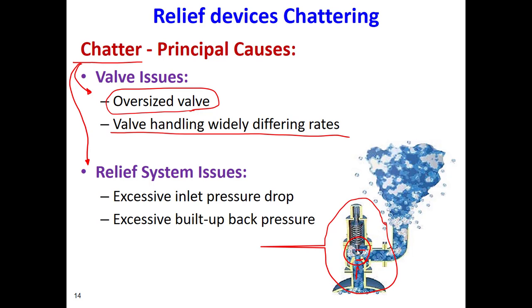Okay, in the inlet and outlet of the valve, that will lead to chattering, or if there is a big back pressure, an excess back pressure in the relief section of the relief valve somewhere here. So those are also cases where we might have chattering, so we have to avoid it.